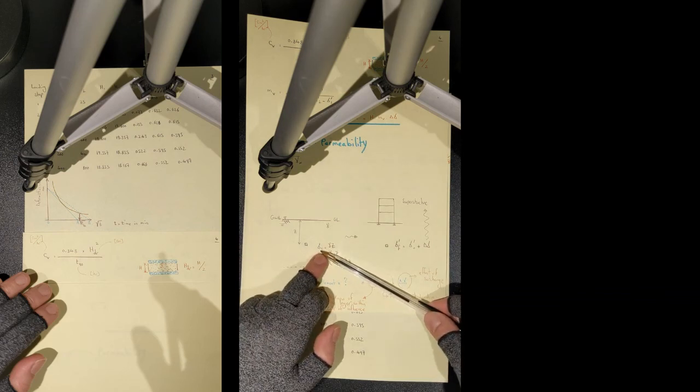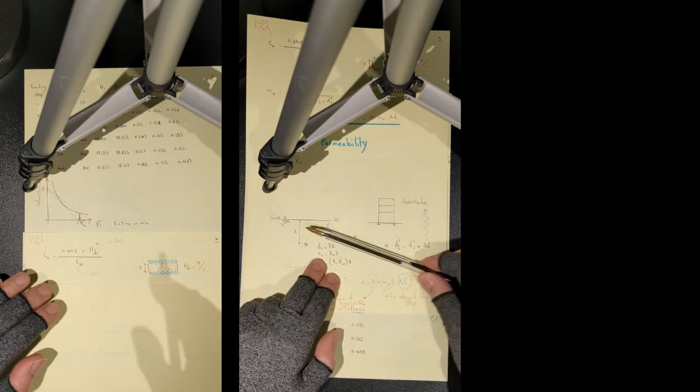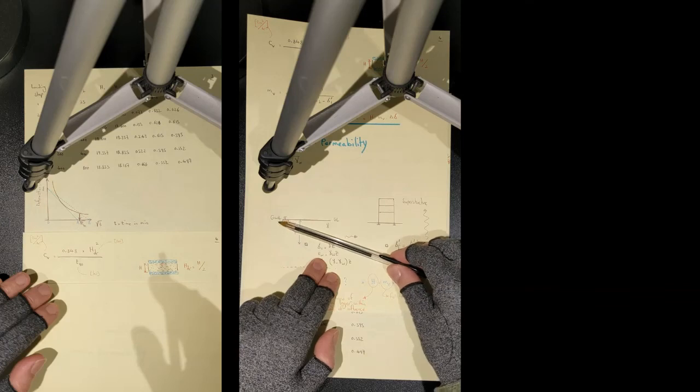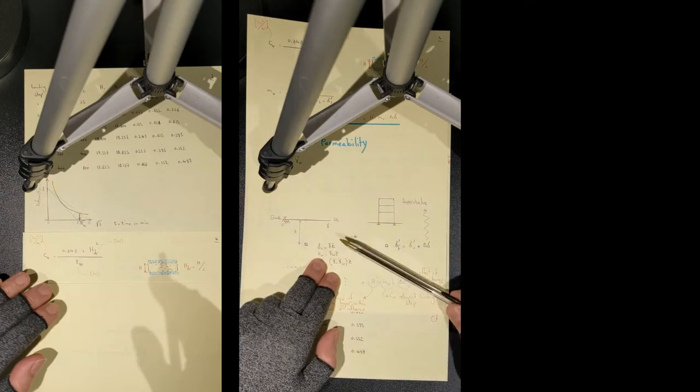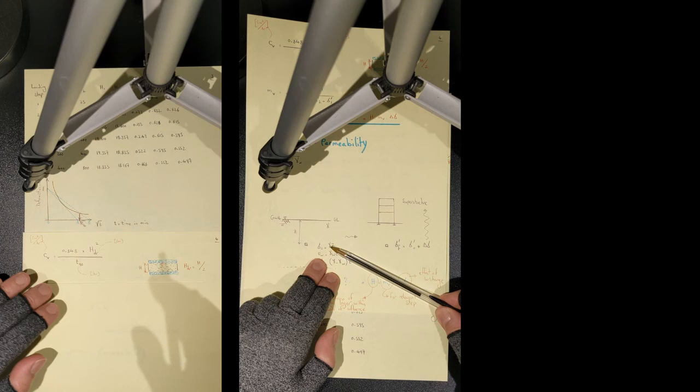Now, your Z is the distance between your soil sample and the ground level. And you know that the unit weight of soil is gamma. So you know that the total vertical stress before construction is sigma naught, that is equal to gamma times Z, simples. You also know that, since the groundwater level is standing on ground level, your pore water pressure is equal to gamma W times Z. Z is equal to ZW.